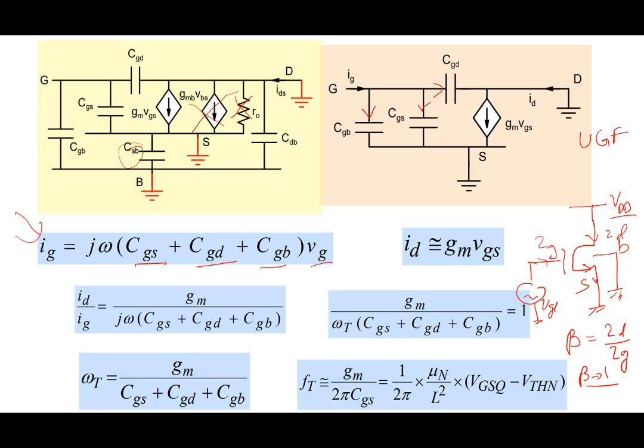And the drain current, you can see 2 components. One is going here, and the other one is going here. There is a possibility of drain current flowing from here, but this component is much smaller than this component most of the time. So that's where we have written ID equal to simply GM times VGS.